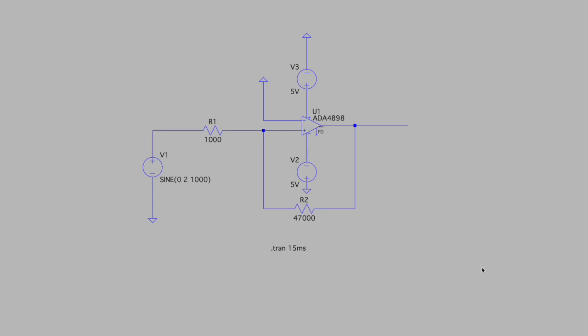This video will explain my Lab 4 for the IE1206 Embedded Electronics course. For this lab, I've built a Schmitt Trigger using components provided in the lab kits. A Schmitt Trigger converts a slow changing input signal, like that of a sine wave that I've used in this lab, into a clean and sharp digital input with no or incredibly limited ambiguity.